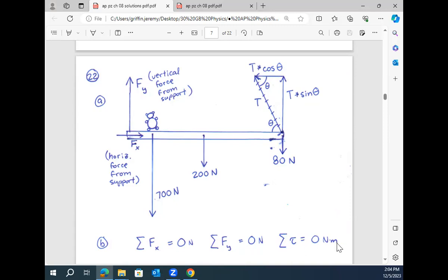Now, you guys had a 2-day lab on torque, and you had a seesaw version. You had a scaffold version, which actually looks pretty similar to this. And I was telling you guys, you could sum the torque about any point, and it would always zero out. I could pick this point, this point, this point. I could pick a point off the system, like over here. The torque still zeroes out. But sometimes there's a most intuitive point to sum the torque about, which would probably be this hinge point, and sometimes there's a mathematically convenient place to sum the torque about, which happens to be the same point.